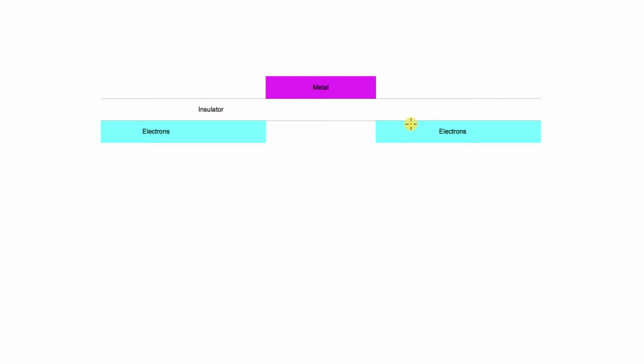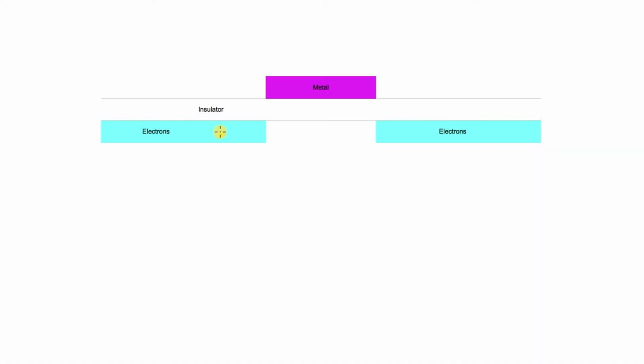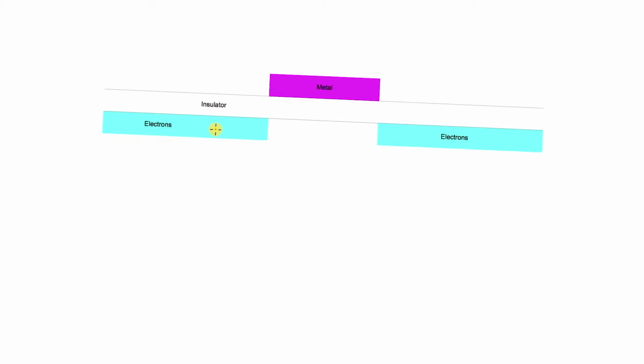Normally in silicon, all the electrons are tied up holding the crystal together. But if we substitute for a silicon atom, an atom like phosphorus that has one more electron, then it can donate that electron and let it go free, and it can join the other electrons and flow, acts just like a metal. So we have two such regions here. You can think of them as metals. They act just like metals. If we tip the picture just a little bit, then they'll flow in the direction downhill. Just like water, if this was water, you tip it a little bit, it'll flow downhill.